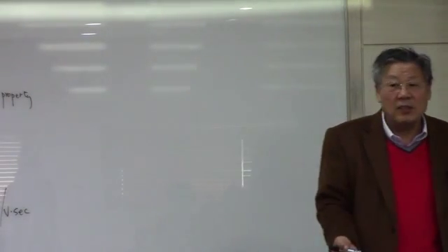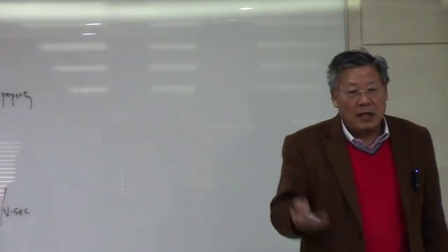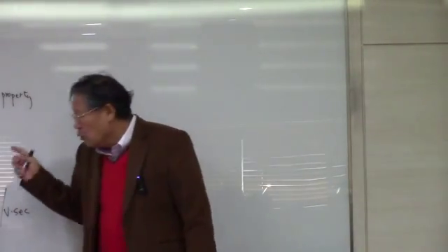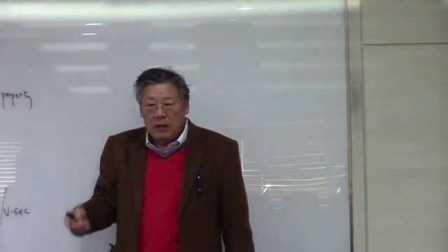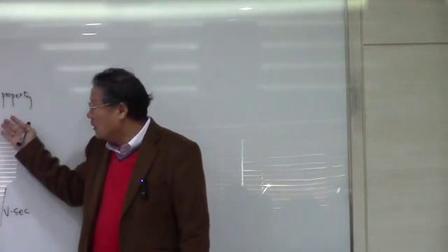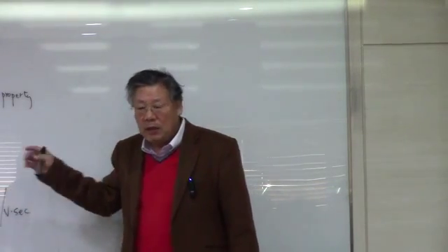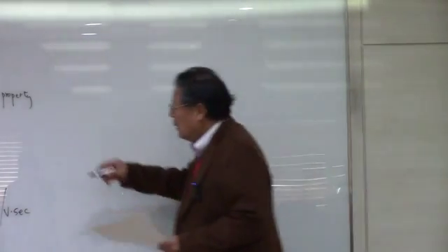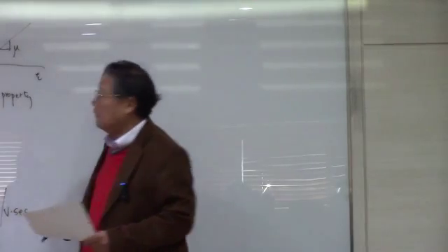So we cannot generally say the velocity of electrons in the silicon. But if you normalize the velocity with the electric field, then we have a material constant like mobility. So that's why we set up the term mobility, and this slope of velocity versus electric field is going to be the mobility.